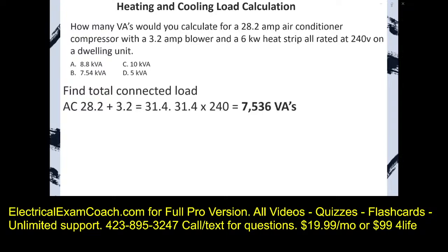We take our amperages and we add them together. Then we need to take and multiply that by the voltage to convert it over to watts. And we end up with 7,536.